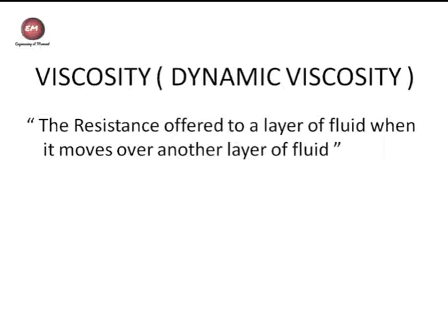Viscosity is a resistance, just like friction is a resistance. The definition is the resistance offered to a layer of fluid when it moves over another layer of fluid. Means when fluid is in motion, one layer of fluid offers a resistance to another layer of fluid due to motion, and that resistance is viscosity. You can also call it dynamic viscosity.